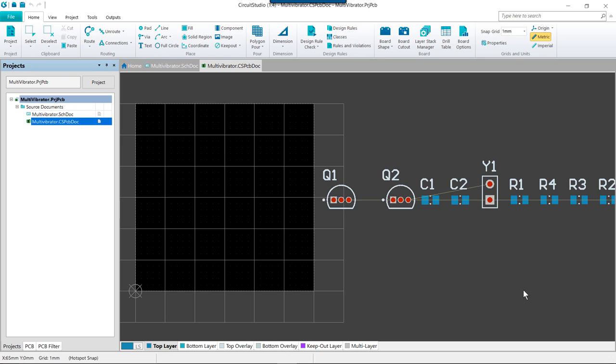For a simple design such as this, there are no specific design requirements that dictate what placement grid should be used. As the designer, you decide what a suitable placement grid would be. To simplify the process of positioning the components, you can work with a coarse placement grid, for example, 1 millimeter. So let's go ahead and confirm that the snap grid is set to 1 millimeter on the Home tab of the ribbon. The components in the tutorial can be placed as shown in the provided image, and of course you can follow along with the placement with me.